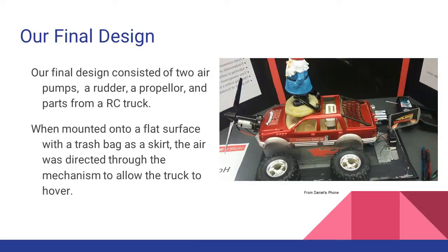The design that we decided on consisted of 2 air pumps, a rudder, a propeller, and various parts from a remote control truck. As you can see, the trash bag is attached to the bottom of a flat surface that allows air to freely flow to fill the space in the trash bag. After tweaking the design a few times, we felt that we had reached an equilibrium in air distribution, weight distribution, and friction.